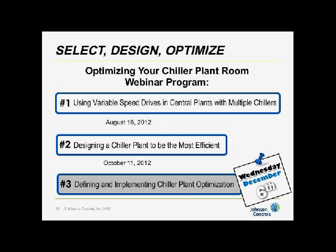What is the cutoff temp for cooling tower? I'm assuming that you're talking about the minimum supply temperature and not freeze. So we'll address it with minimum supply temperature. That is whatever the minimum supply the chiller that you are serving can handle. If the chiller can handle 50 to 55 degrees, then the minimum supply temperature is 50 to 55 degrees, whatever the number is. Every chiller's got a number, so just ask the manufacturer for it.